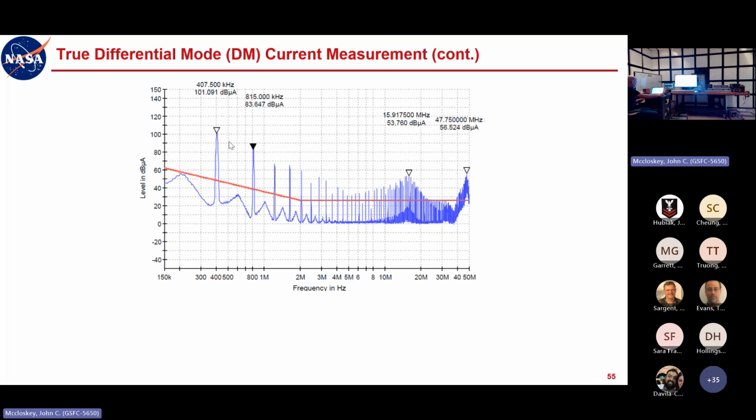So if we're higher than 6 dB, then something's goofy with our measurement setup. This is all part of my whole test and measurement philosophy: you should at least have some rough idea of what to expect, because if it's beyond what you expect, then you need to really scrutinize your measurement setup. If we're getting like 10 or 20 dB higher here, that can't happen. There's something that you're not doing right in your measurement setup.